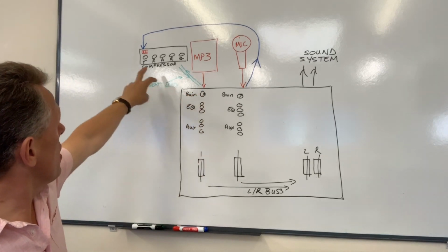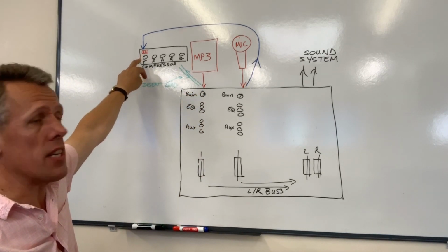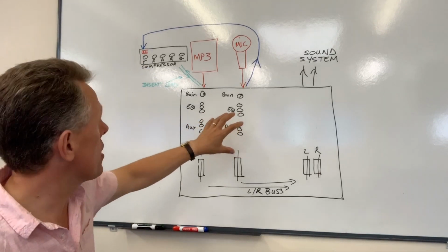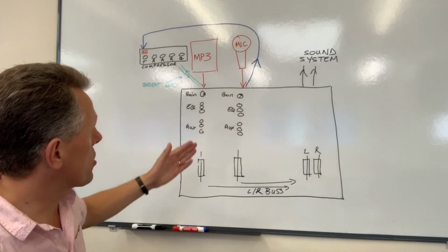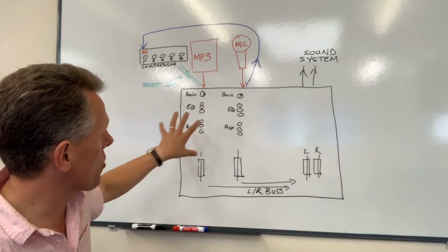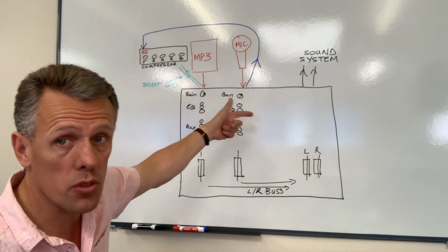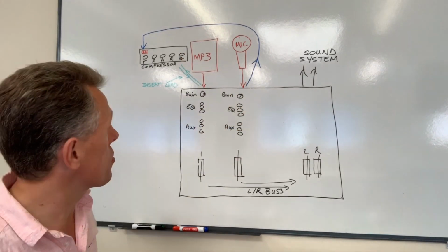We would then, and I've drawn here a little button that says SC, stands for sidechain, because what we would then do is from our actual vocal mic, we would connect a lead from that, so that's still routed to left, right. So we would come out of, say, for example, an auxiliary, we could come out of direct out, or even a group if the vocal's routed to a group.